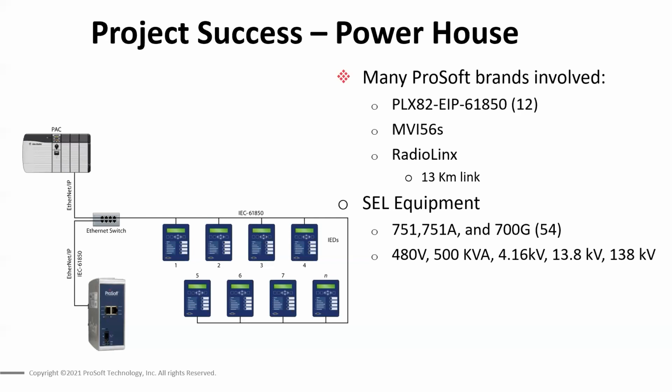A couple more questions came in. Currently, the MBI94 MCM Modbus is replaced by a PLX31 EIP MBS4. Is any module in the MBI series coming to fit in a ControlLogix rack for 61850? Yes, for 61850, the ControlLogix module is that new MBI56E-61850C module.